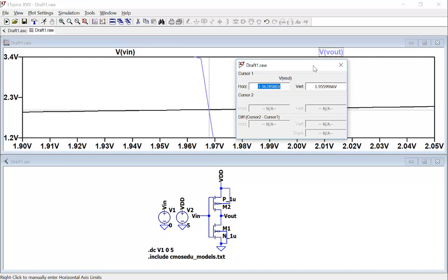Why? Who is pulling that point to ground? Yeah, the NMOS is pulling that to ground, which means what? It means you have a strong NMOS. Strong means you have a wider channel. You can imagine it's just like two people, one on the top, one on the bottom. Whoever is stronger can pull it down to ground early or pull it up early.